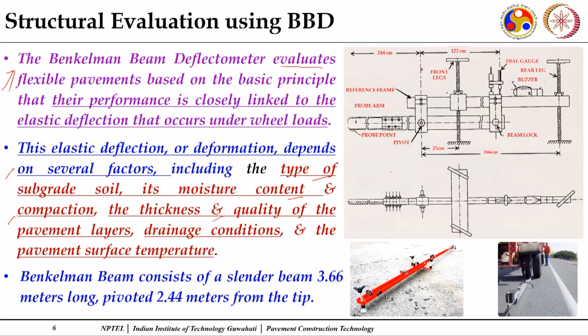Then the other part is the thickness and quality of the pavement layers: the different layers, your granular courses, sub-base courses, base courses, binder courses, wearing courses, so their thickness and their strength. Then the drainage conditions, how well the pavement is drained, and the pavement surface temperature, because specifically the binder stiffness changes with the change in temperature.